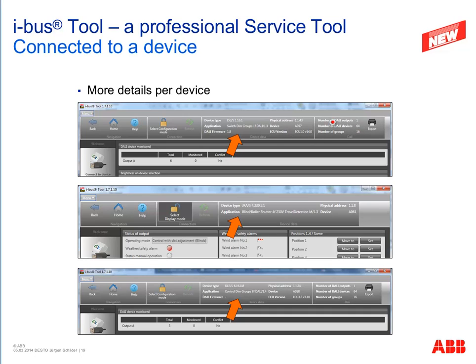Here on the right side we get the number of DALI outputs, 1 output, 64 devices, 16 groups. Or here in the middle we have a screenshot of our blind roller shutter actuator. So we get here the name JRA/S and the name of the application, and here the version 1.3. Or here the screenshot of the DALI light controller, here also the name of the application, and so on.